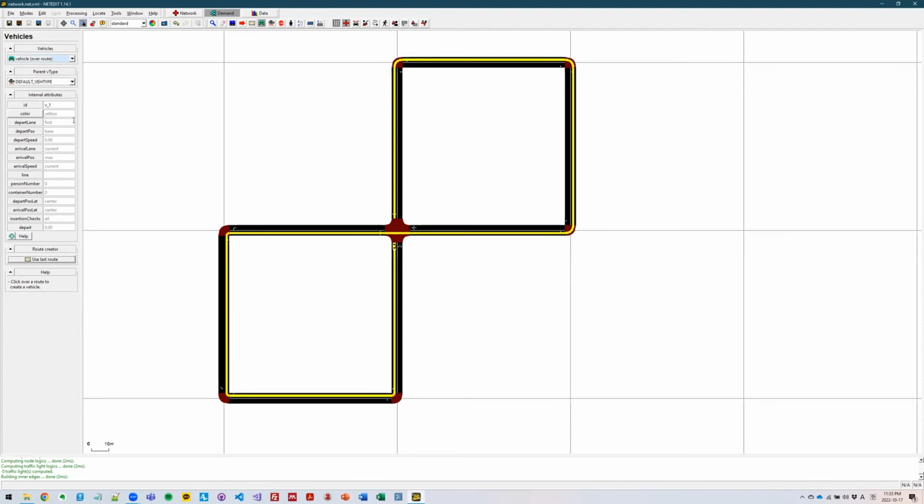And there is another mode in SUMO. So this vehicle will create the trip. So it will just create a single vehicle like this. But if I change to this flow mode and over route, then there are other options. So in this flow, it will start from the beginning and it will end at 3,600 unit time, and they will create 1,800 vehicles per hour. So maybe I can just adjust 100 vehicles per hour. And I can also assign this flow to the route. So we have two traffic flows. The first one is flow, and the second one is the trip.